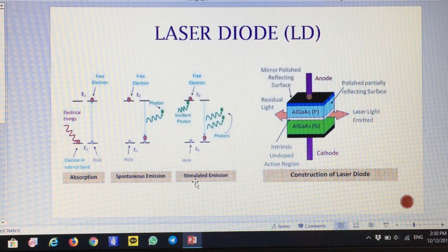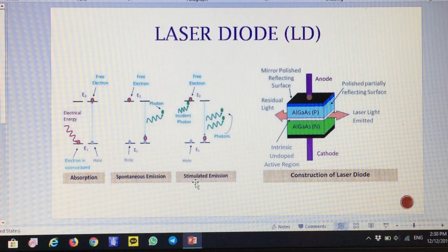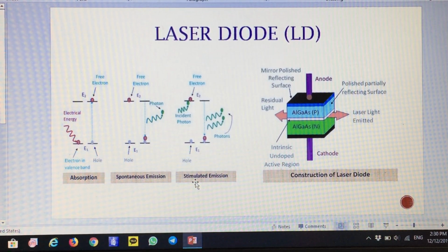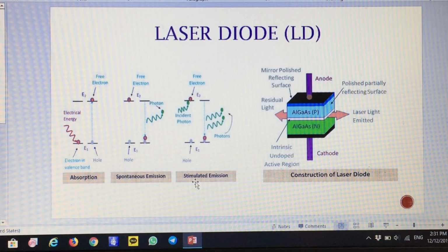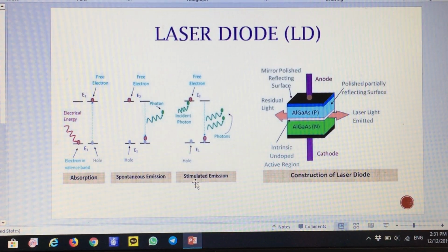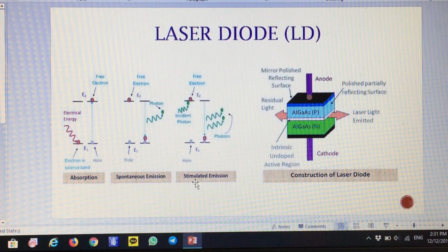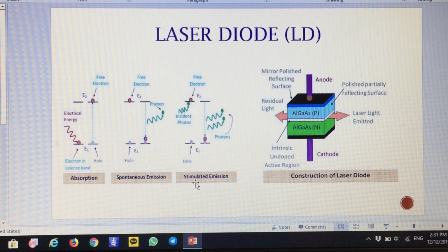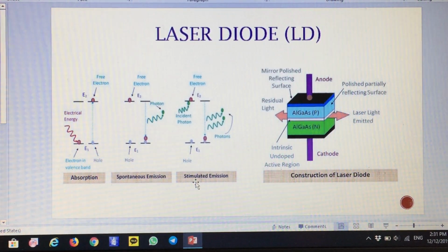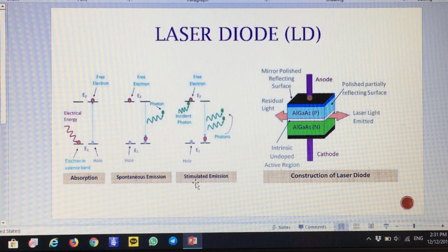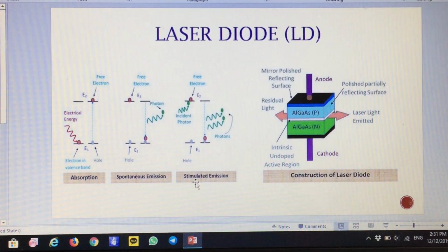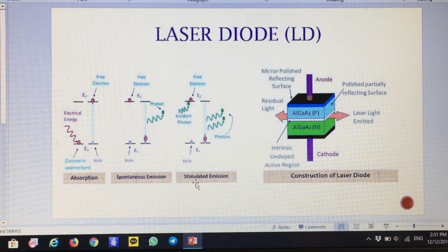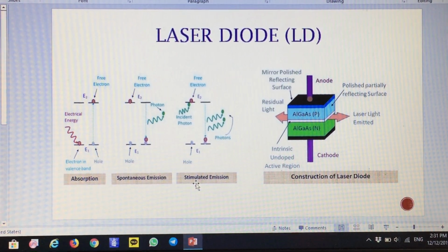A laser diode is made up of two layers of semiconductor, p-type and n-type. The layers of semiconductor are made of gallium arsenide doped with different materials. The laser diode is forward biased by an external voltage. Then electrons can move through the junction and recombination occurs. As forward current increases, more electrons enter the depletion region and cause more photons to be emitted.